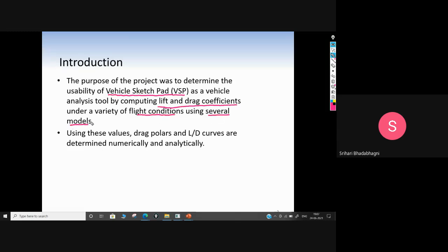The various flight conditions are accelerate, climb, subsonic cruise climb and patrolling, subsonic penetration, delivery of expendables, supersonic penetration to the escape dash, climb, subsonic cruise climb, descent, and finally landing.